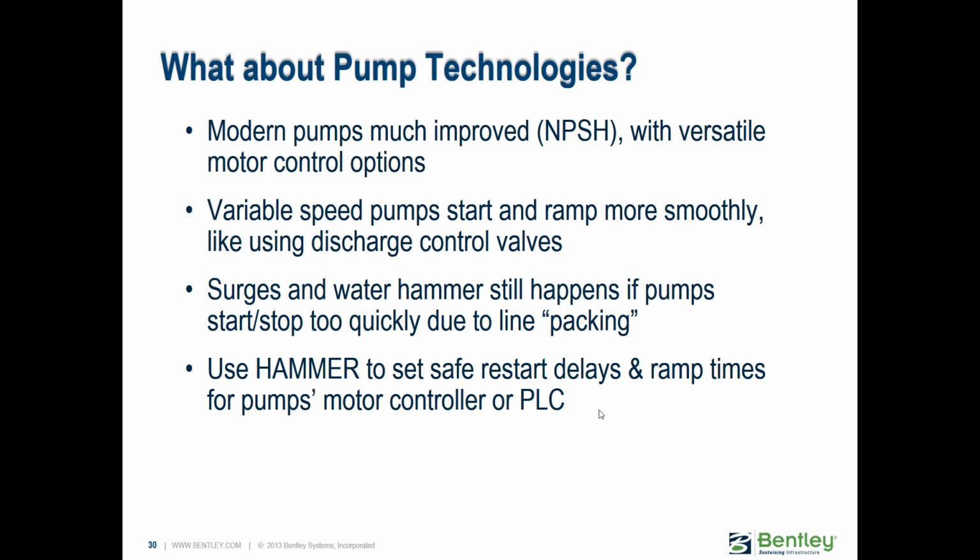Pump technologies: a lot of pumps have new technology, but water hammer can still be a problem if they start or stop too quickly due to that line packing effect. So you're not really safe just because you have a new pump. And you can model soft starts with Hammer to see if it's okay or not.